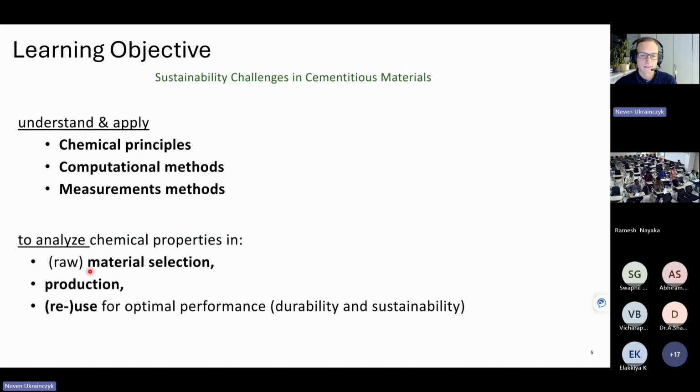We have these supplementary cementitious materials, for example. We can also use secondary industry wastes, or byproducts. If they are used, then they are not wastes, they are byproducts. And you can, for example, carbonatize them, so you can completely avoid clinker, and you can use slags, for example, with carbonation, and those are carbonatable binders. So you don't even have clinker, you just use raw material, and you can utilize the CO2 to produce materials.